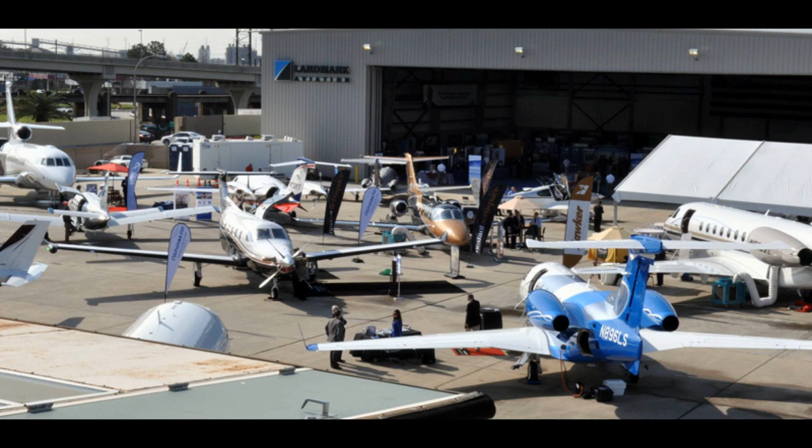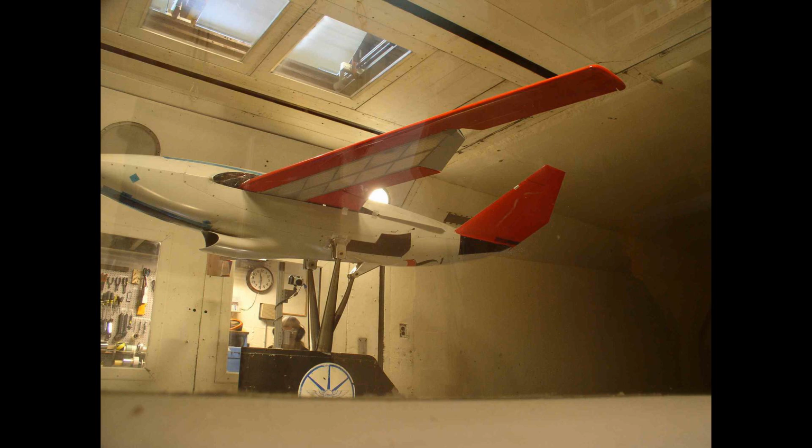In particular, the position of the center of mass (COM) of an aircraft is usually measured relative to the MAC as the percentage of the distance from the leading edge of MAC to COM with respect to MAC itself. Note that the figure to the right implies that the MAC occurs at a point where leading or trailing edge sweep changes. In general, this is not the case. Any shape other than a simple trapezoid requires evaluation of the above integral.